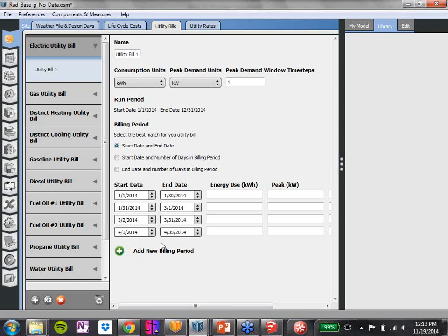And so this is when, if you're analyzing a building, you either ask the building owner or you make a request of Idaho Power to please send us your data. At the very least, you can just take your straight-up bills and look at your energy end use, and that's what I'm going to approximate right here.